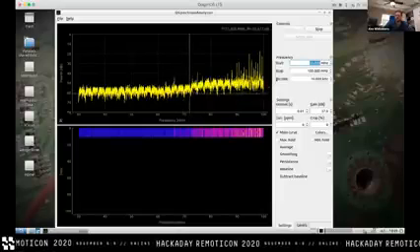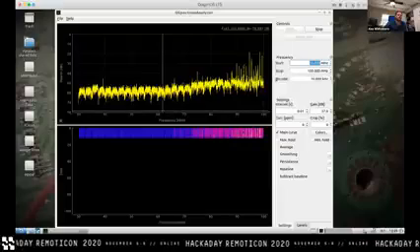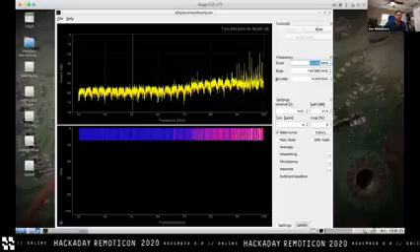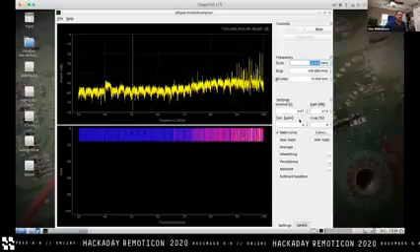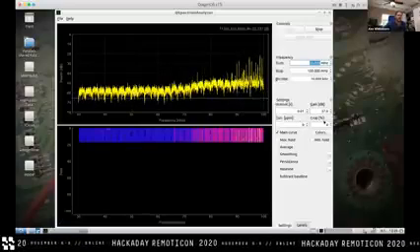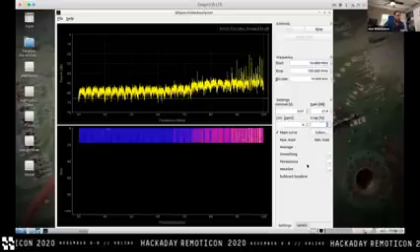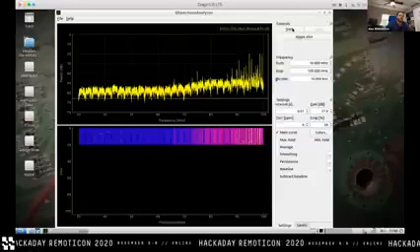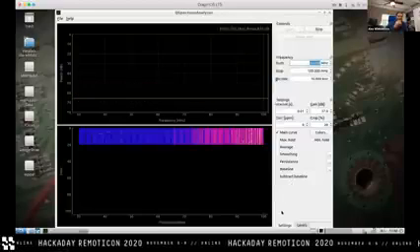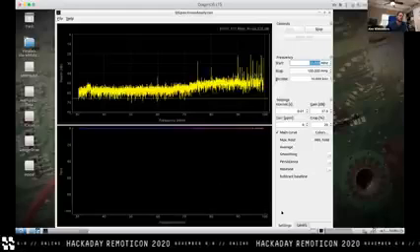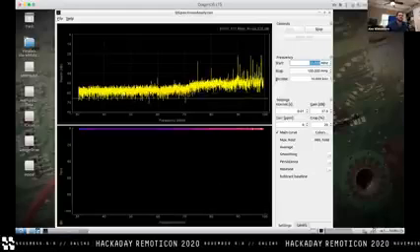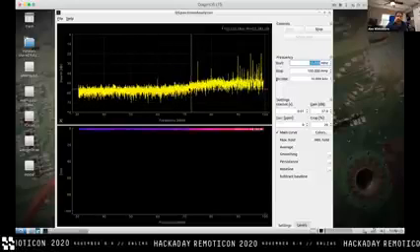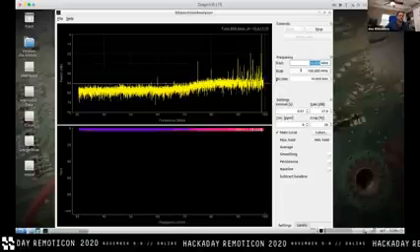That's because the spectrum captured by the SDR actually falls off towards the edges of the real-time bandwidth, and we can see that in the spectrogram with these darker lines. So even beyond this, what we actually want to do is add a crop. I'm going to go with 20%, which basically just overlaps the adjacent spectrum chunks by 20% and cuts them off next to each other to try to level that out, at the expense of taking longer to capture spectrum. But that sure looks a lot flatter, doesn't it? So these are pretty good settings. This is what we'll go with.